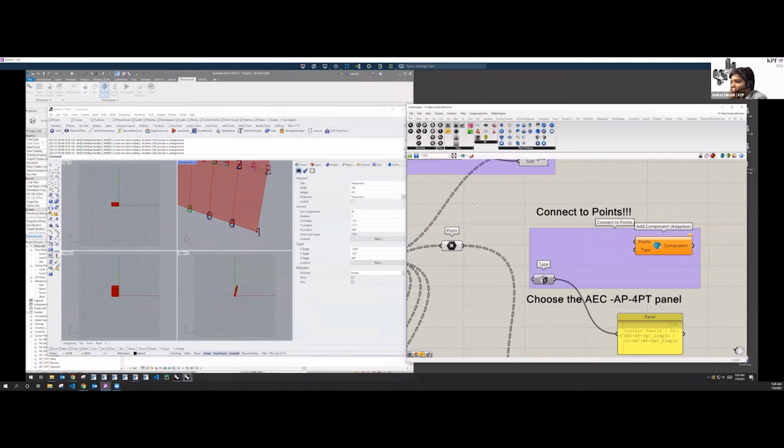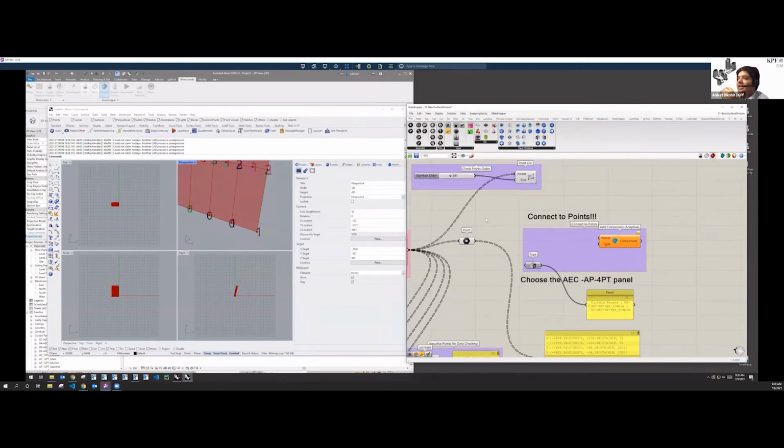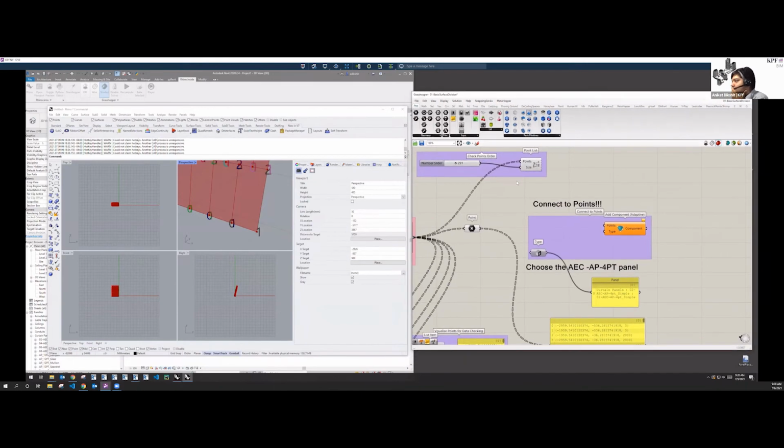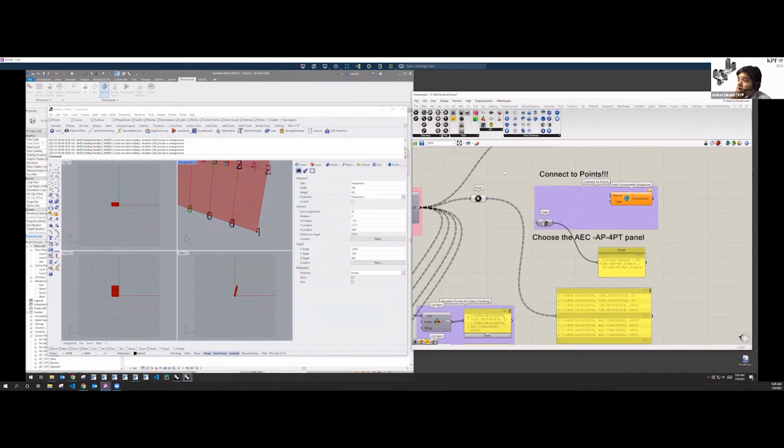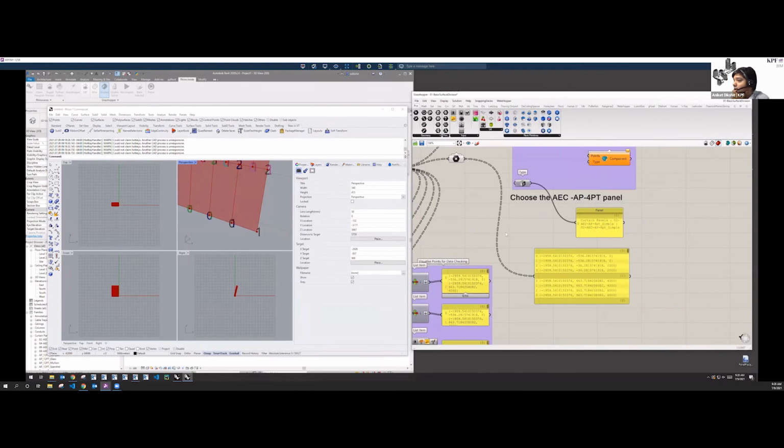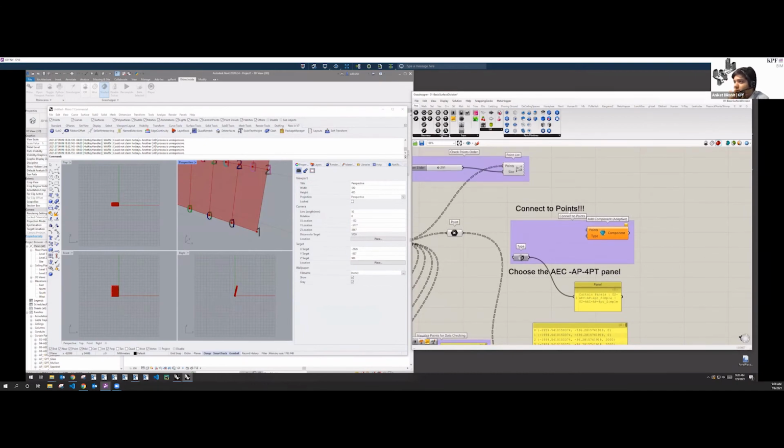Thank you for the in-depth knowledge on adaptive panels. So now once we have our adaptive panels ready and we have the Grasshopper condition ready, now comes the time to make everything come together inside of Revit, for which we're going to be using Rhino.Inside. I always make sure that the points are ordered in the correct order before I push the button on the adaptive component, because if you're putting in 9,000 panels and the points order is incorrect, that means all of your adaptive panels are going to be wrong.